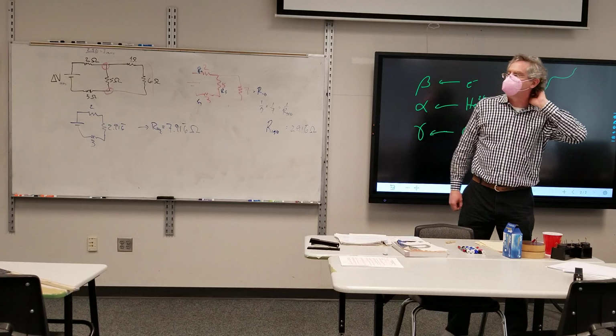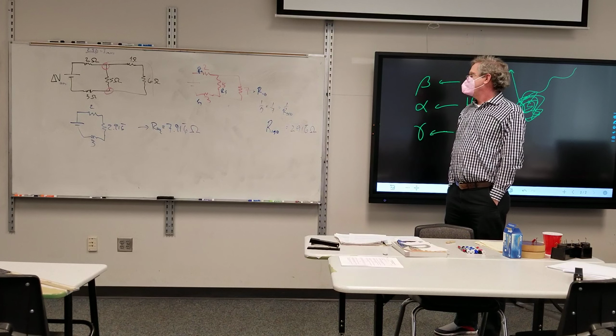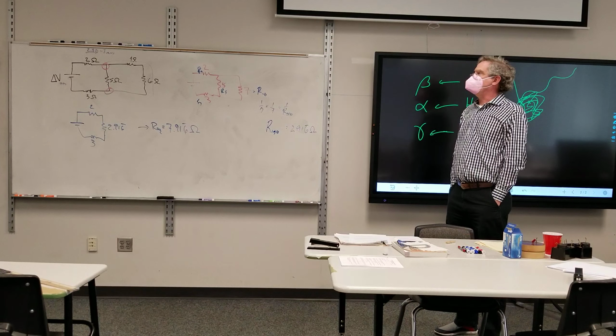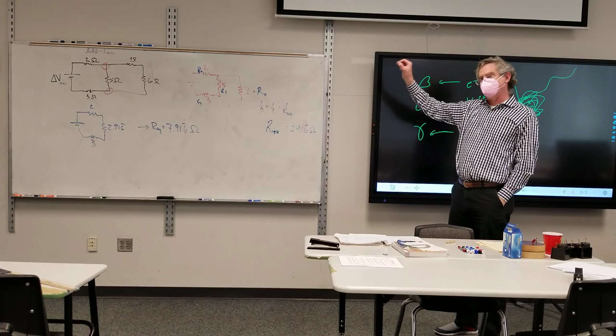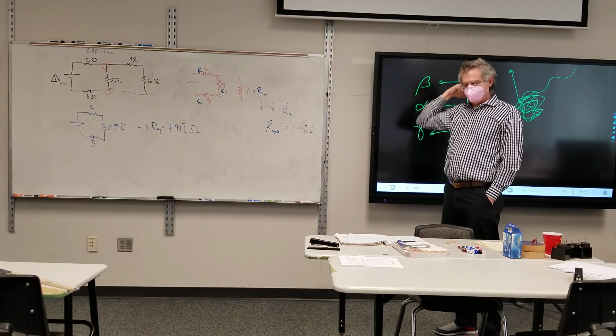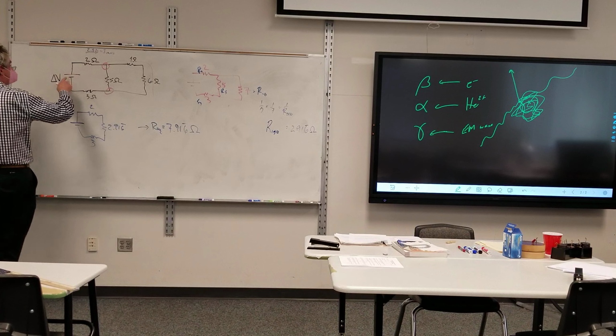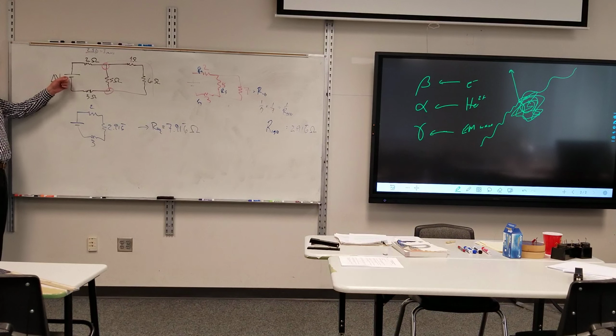Do you multiply that by the total resistance or just by the resistance of the light bulb? The resistance of the light bulb would just tell you the change in potential across just that resistor. Okay, so it's the total? Yeah, in this case the current flowing across here is the same as the current flowing out of here, so all I need to do is figure out the current flowing out of the battery. I need to know what voltage will produce 2.4 amps coming out. Is that light bulb, it takes over the resistor, so the 2 ohm resistor is gone? Or is it still there? It's still a 2 ohm resistor, it just happens to glow.